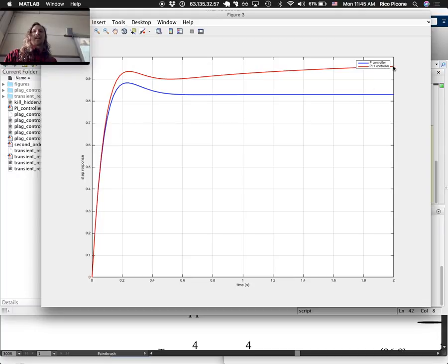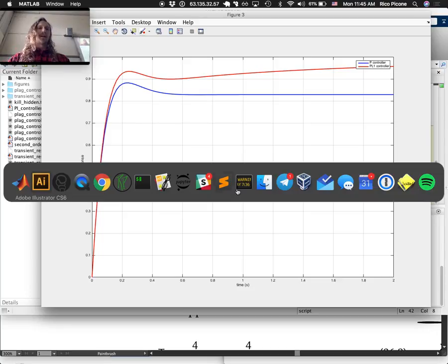And the steady state error here, I would say, is still maybe going to be like 3%. It needs to be 1.8%, right? So we're not quite there. We could simulate out further, but we kind of want this to happen faster. Let's just assume that we want the steady state error to go away faster. So we're going to move these leftward for our second design.